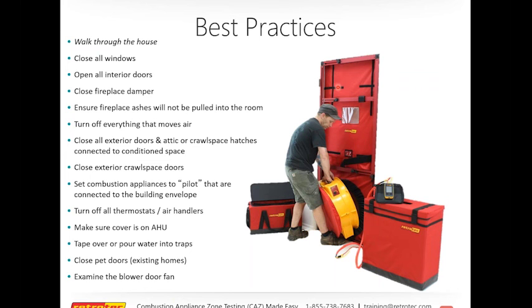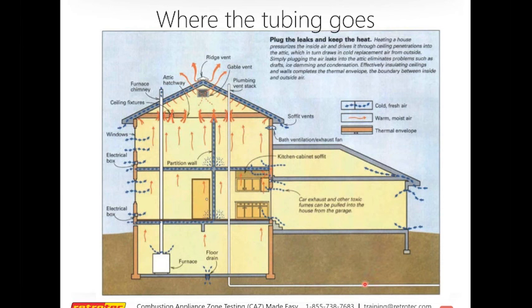The initial house setup for the blower door, or at least the shell of the house, is the same as for the CAZ, but not for the duct tester. That's different. Okay. So the first thing I want to recommend to you to save time is to set up the blower door and the combustion test at the same time. The next thing I want to recommend to you is where to set it up.